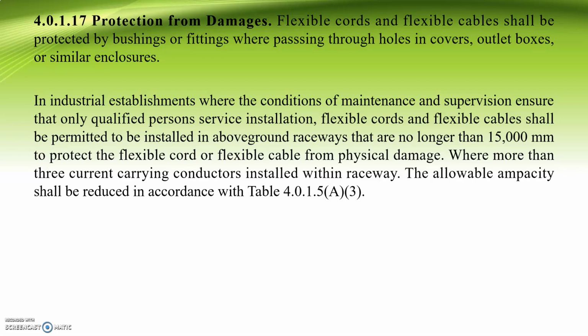Chapter 4.0.1.17, protection from damage. Flexible cords and flexible cables shall be protected by bushings or fittings where passing through holes in covers, outlet boxes, or similar enclosures.